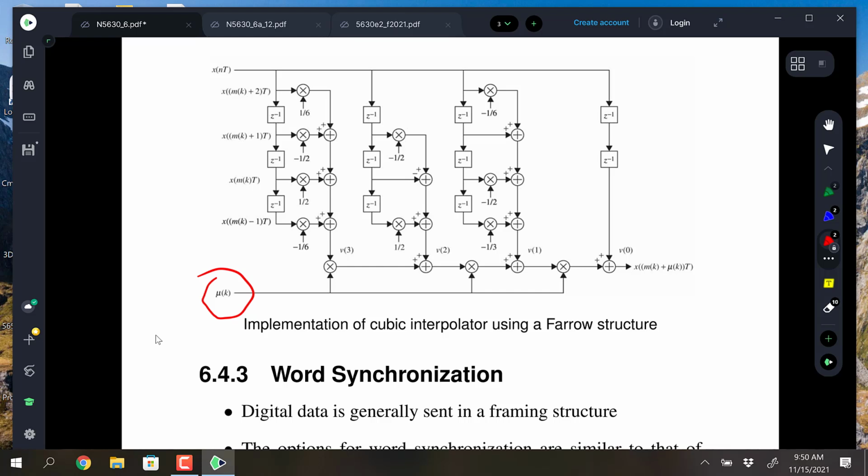And this is the cubic interpolator. The ones that I have in my library or my module are first, second, and third order, so you can choose which one you want to use. The first is much, much simpler, and in my experience when I worked at RT Logic, the guy that was doing the symbol synchronizers there would usually just use a first order interpolator, but you can go up to third order. That's pretty common as well. So I made it programmable.